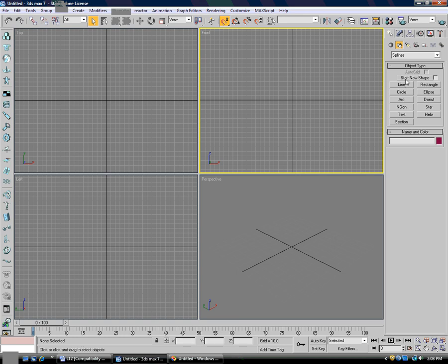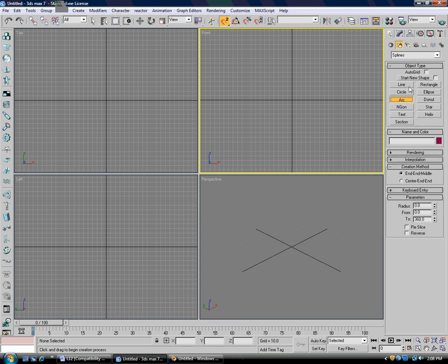First I am going to create an arc on this front panel, so that will create the head of the pawn. So I will start from here and end it at this particular position, and after ending it you can see the curvature. I am setting the curvature by moving the mouse very smoothly like this, and you can have an arc like this.